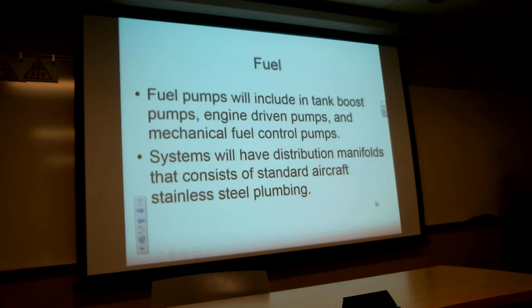So as the throttle goes forward, we're taking this fuel that's supplied to the engine and the fuel control, and we're going to step up the flow incrementally through the fuel control and the FADEC. That's how we increase it. It used to be everything, like I say, was push-pull controls or connecting rods. Now it's all electric. So valves are going to begin to open in sequence 1, 2, 3, 4, 5. As the more valves open, the more fuel flows through the fuel control. Pressure bumps up, the volume bumps up at the same time.